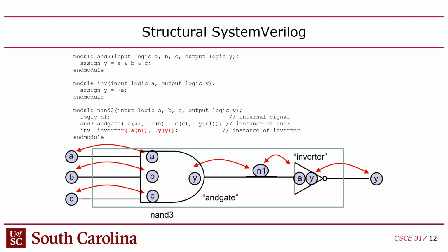That kind of stinks. Well, the hierarchy is in there to make the design manageable and readable and reusable and debuggable, right? But when you put this on the FPGA, it gets flattened into one big rat's nest of wires, right? And those wires don't have this hierarchy, and so 2 of those names are going to go away, right? You can't have 3 names. Eventually, when you put it in the FPGA, it will have a final name that's probably just one of those. I mean, it doesn't have a name at all, technically, but if you go inside a Signal Tap and try to tap it with JTAG, it'll just have one name.